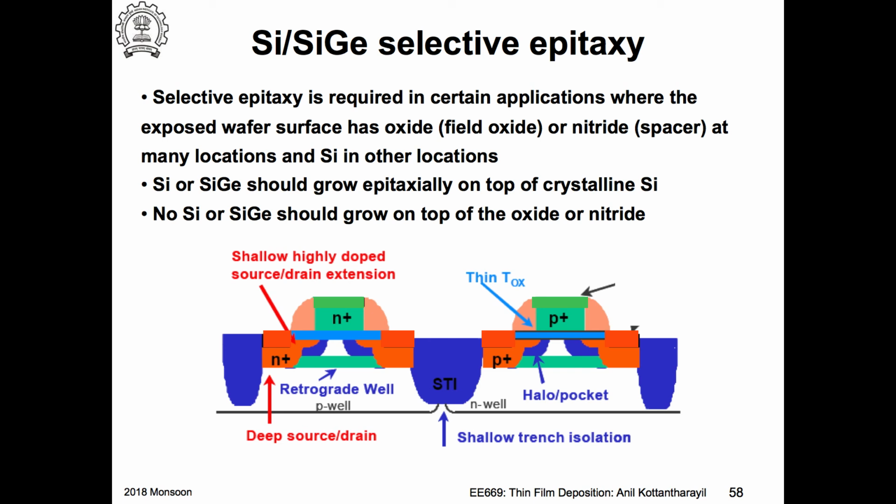One is that it is seen if you have silicon germanium in the source and drain region of a P-channel MOSFET, you can actually enhance the mobility. Okay, not so for the N-channel MOSFET. So then the problem for epitaxy is restricted to this. I should be able to grow an epitaxial layer here, okay, and here, nowhere else.